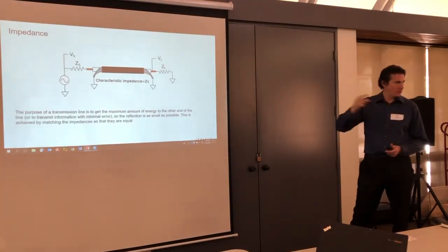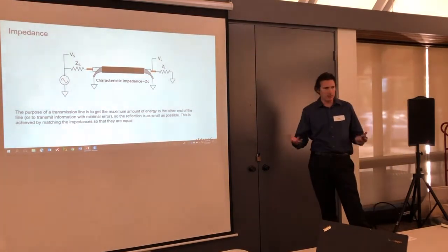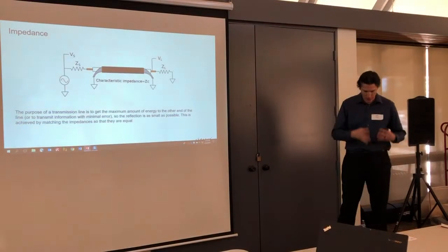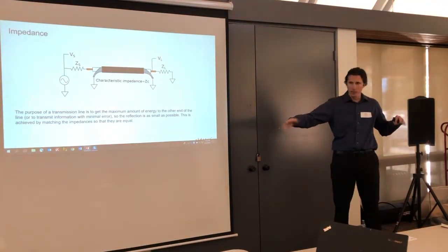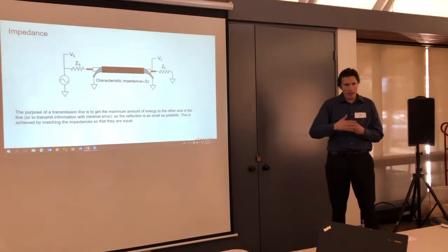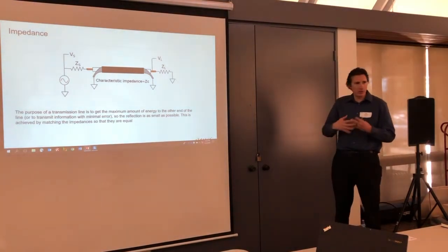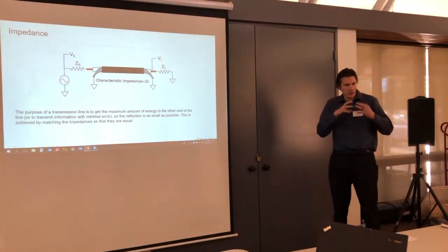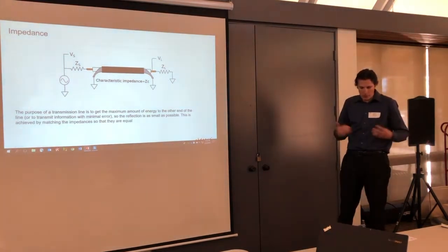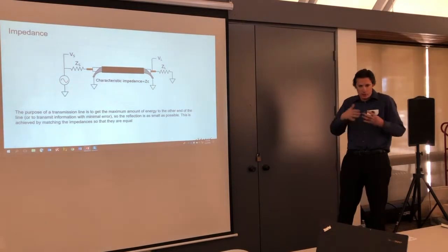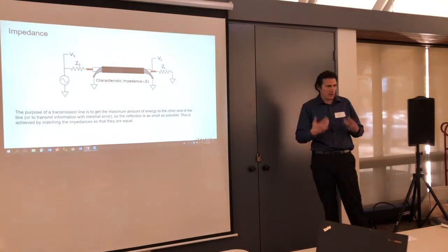And I'm also going to be clocking through these presentations kind of quickly because we don't have a ton of time for it. So the second thing to think about is impedance. You have a driver and a receiver. Those things have some sort of characteristic impedance already. You want the transmission line to match that impedance, so there's not an impedance discontinuity, because impedance discontinuities can also cause reflections in the signal or the energy that you're trying to propagate from the driver to the receiver. It basically looks at an impedance discontinuity as if it's some resistor or some little wall that it has to get through, which also makes the receiver not see the desired effect of what the